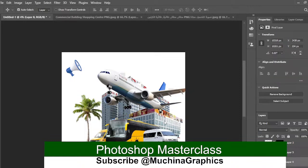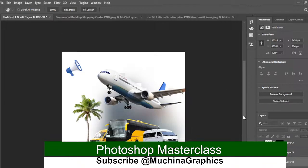So I'm going to select this building and then I'm going to blur it so that my images, the rest, can be clear. So I'm going to filter, blur, Gaussian blur, and then I'll be able to use it just a bit somewhere there.